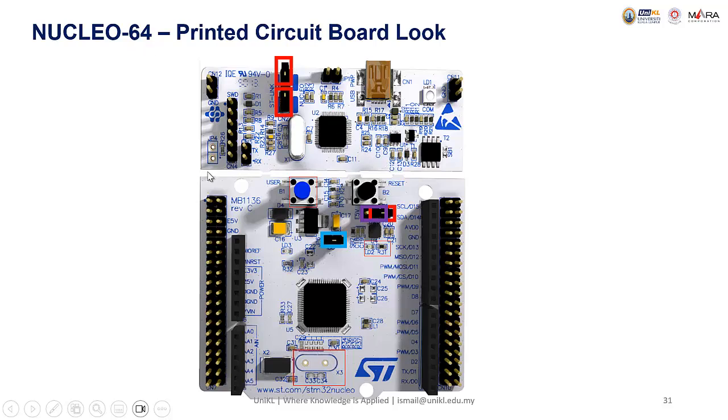What you can see is that it has two parts, the top and the bottom. The top part is the downloader and debugger. Here we also have the converter from low power TTL to RS232, so we can connect this directly to the PC, using the UARTs for serial communication. We can also use this to download the executable file into the processor.